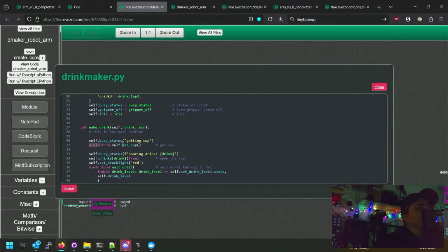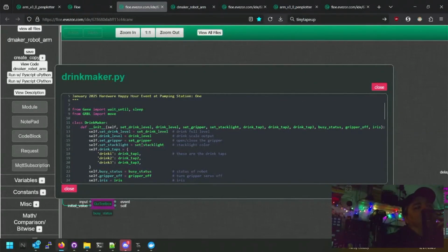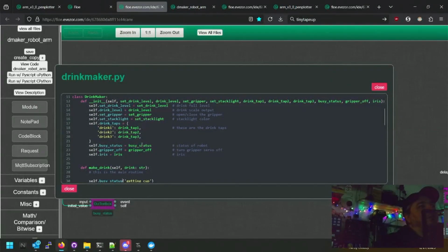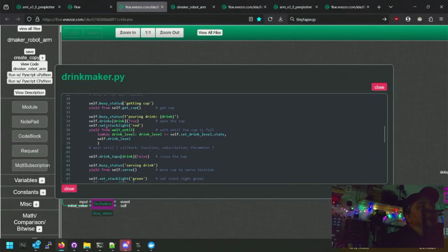None of this kind of events ends up in your event loop per se, because anything that you're waiting for is handled somewhere else, whether it be actually waiting for FluidNC to finish a move and get back to say that, okay, the robot has actually reached the position that you told it to get to, or some of these wait commands or sleep commands.